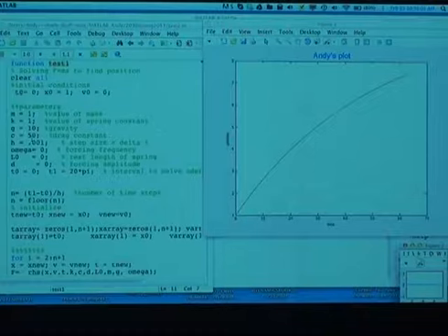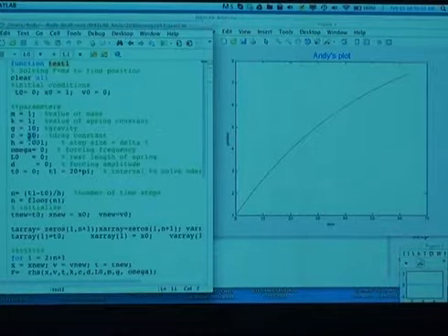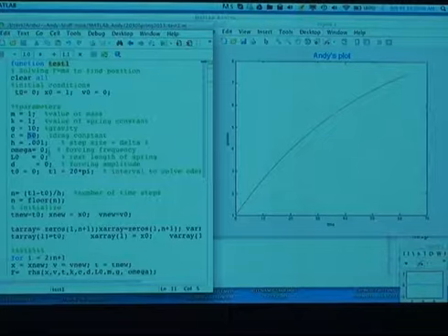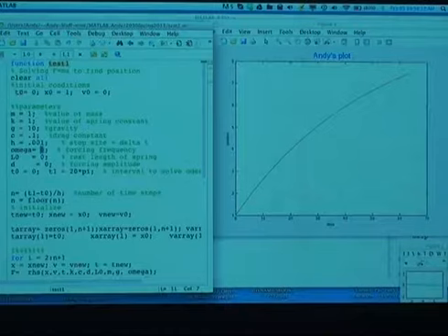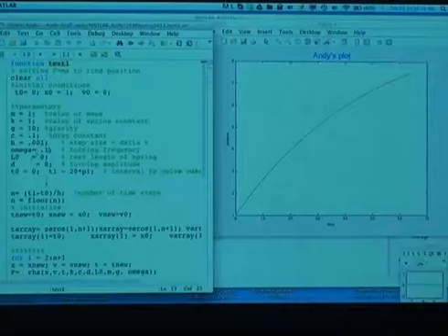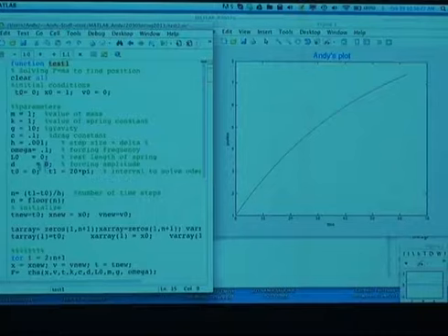Now let's look at the forcing side of things. Let's go back and make the damping pretty small, 0.1. And now let's force this at some omega, which is not 0. See, omega equals 1 was the natural frequency of this thing, so let's put in omega of 0.1. So it just oscillates a little bit. But let's make the amplitude of oscillation pretty big so we can see it. Let's put it in like 2.